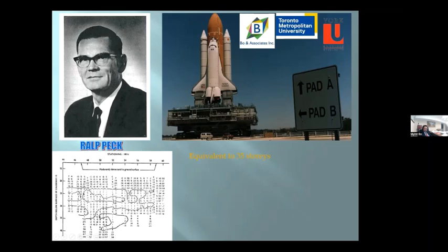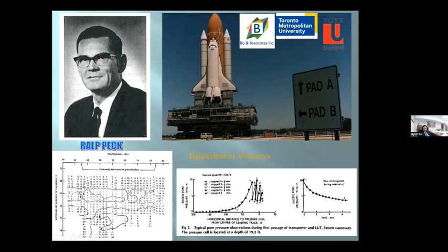What he did is he installed piezometers in the silt deposits. And then he took control of the driver of the disc crawler and asked them to drive until very close to the critical pore pressure. And when the monitoring observations showed it was about to reach the critical pore pressure, the driver was asked to stop, until the pore pressure dissipated to an acceptable level. And then he asked them to drive again, and then stop, drive, stop, and so on.